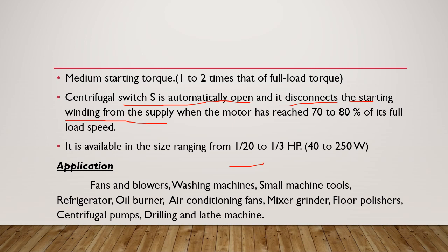It is available in sizes ranging from 1/20 to 1/3 HP, that is 40 to 250 watts. The applications of this motor are fans and blowers, washing machines, small machine tools, refrigerators, oil burners, air conditioning fans, mixer grinders, floor finishers, centrifugal pumps, drilling and lathe machines.